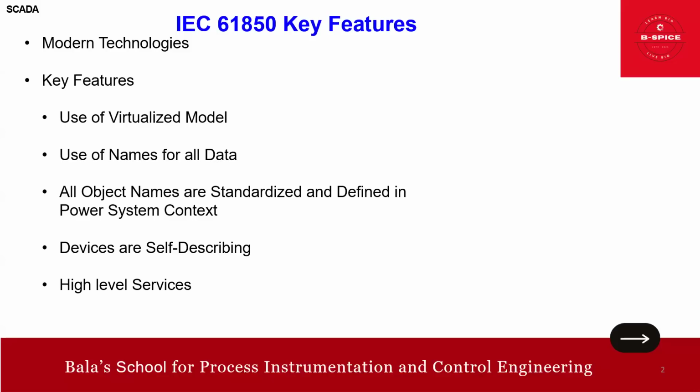Again, we'll talk about GOOSE here. GOOSE is nothing but the Generic Object-Oriented Substation Event, a communication protocol defined by the IEC 61850 standard. It is designed for fast and reliable data exchange between intelligent electronic devices, IEDs, in a substation. Just imagine, friends, high-speed communication.